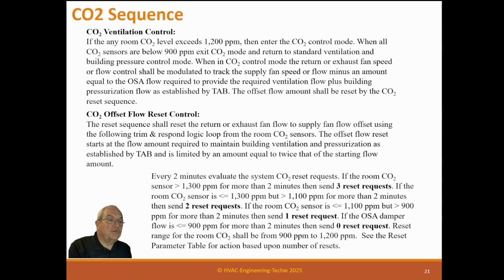If the room CO2 sensor is greater than 1,300 parts per million for more than 2 minutes, then send 3 reset requests. If the room CO2 sensor is less than or equal to 1,300 parts per million, but greater than 1,100 per million for more than 2 minutes, then send 2 reset requests. If the room CO2 sensor is less than or equal to 1,100 parts per million, but greater than 900 parts per million for more than 2 minutes, then send 1 reset request.